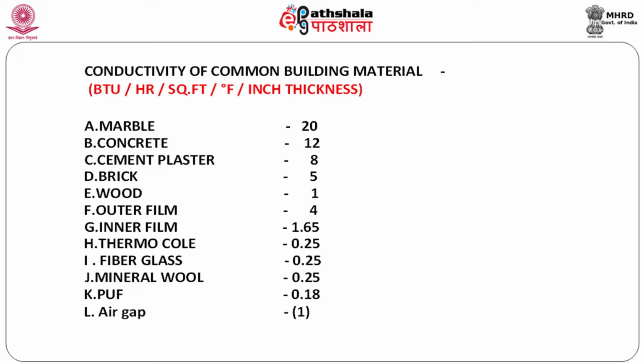What is necessary is not to remember the values that you see against them, but to have a feel for them being good conductors or bad conductors. For instance, it is very well known that if you make an air conditioned room out of a tin sheet, you require a larger capacity, more heat will flow through tin. Substitute the tin with a 9-inch brick, fine, you have lesser heat coming in. Substitute it with 18 inches, you have still lesser heat. What is required is a feel of the material you use and the thicknesses that are required to be able to optimize on the type of construction that you should go in for.